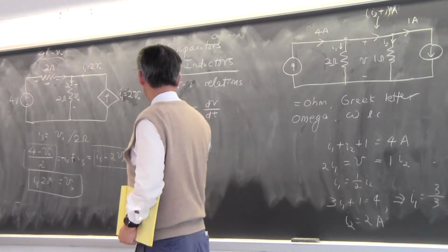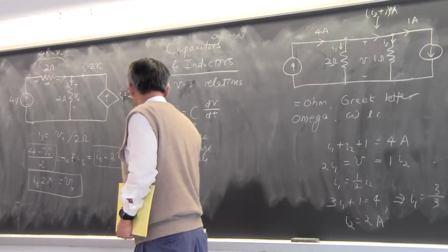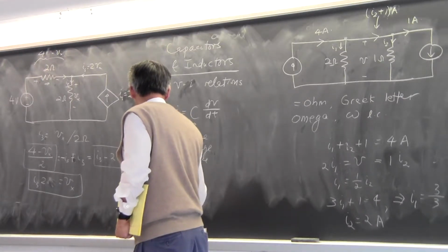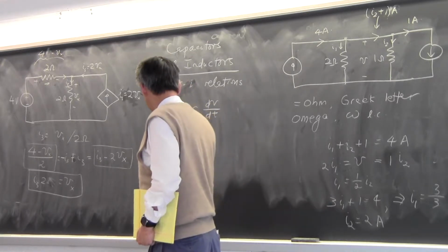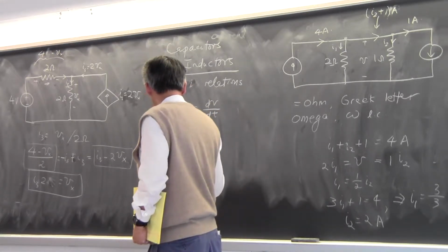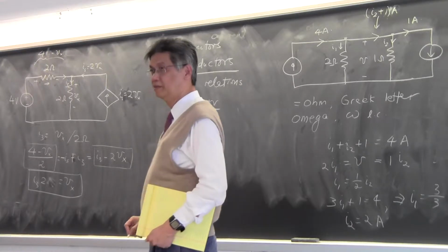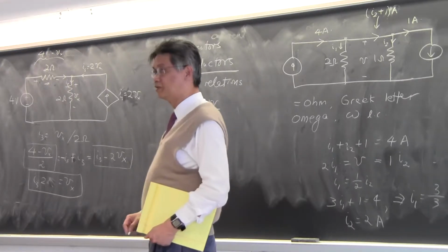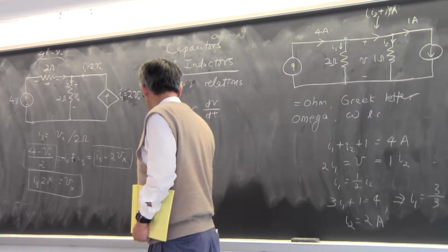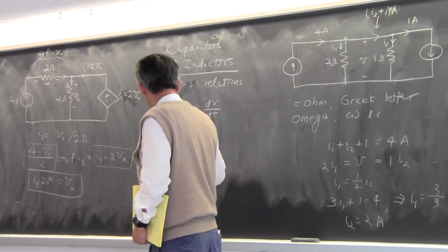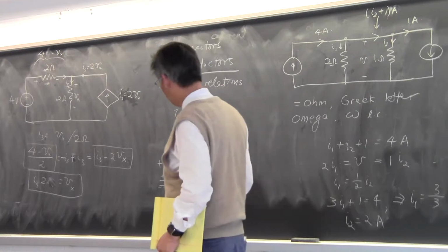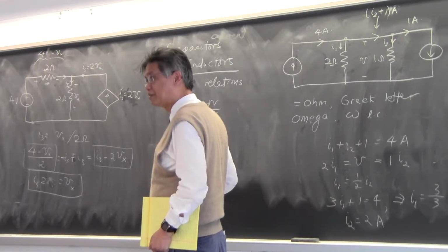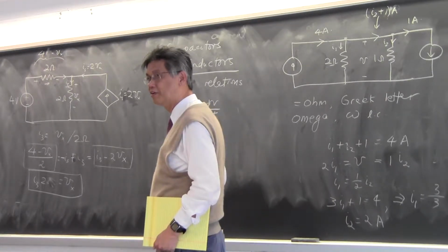Okay, you can apply the voltage to this capacitor. Maybe you can say the bottom one is connected to ground so that this is 0 volt. What happens is that charges will start to accumulate on the terminal connected to a positive voltage. These are positive charges. Okay, current will be flowing into this capacitor. But this capacitor is not connected between the two plates. Eventually the current cannot flow.